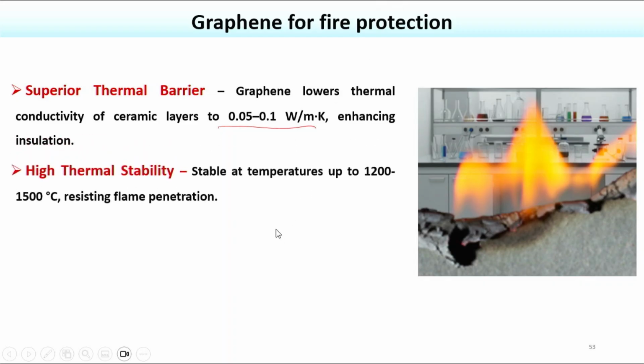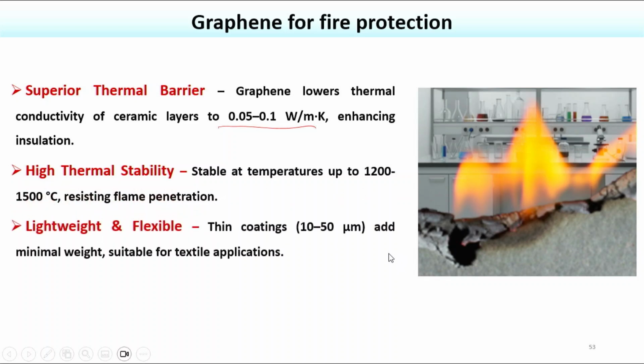It has high thermal stability, stable at temperatures around 1500 degrees Celsius, and resists flame penetration. It is lightweight and flexible, with a thin coating of 10 to 50 micron at minimal weight, suitable for textile application.